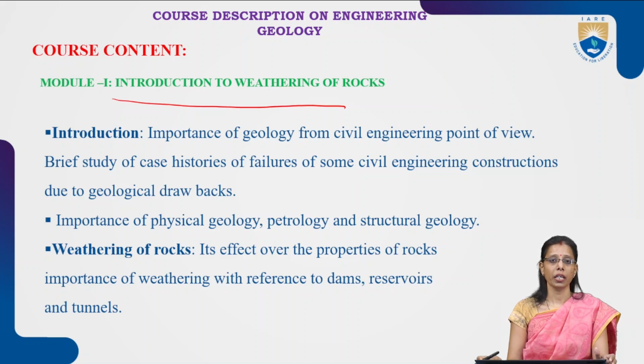The rock will break. How will the rock break? Whenever the temperature is cool, whenever the temperature is hot, in that condition the breakage of rocks will take place. So contraction and expansion of rock will slowly break the rocks. If any type of rock is present there, it can be broken into pieces and it will become soil. So this weathering process is very important when you go for the construction works of dams and reservoirs.